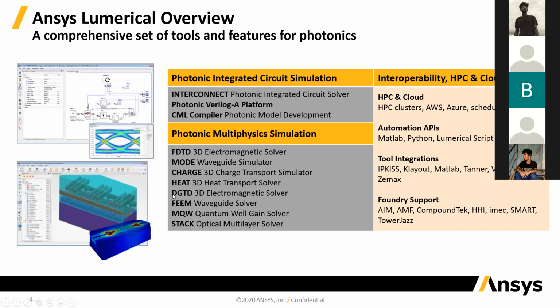DGTD is a solver that's very similar to FDTD in the sense that it also solves Maxwell's equation. However, the difference is DGTD uses finite element mesh as well. So there are some specific applications where DGTD can offer you more benefit, and we'll talk about that briefly. Next is FEEM. This is a waveguide solver again, but it uses finite element mesh, and it resides with all of these other finite element tools.